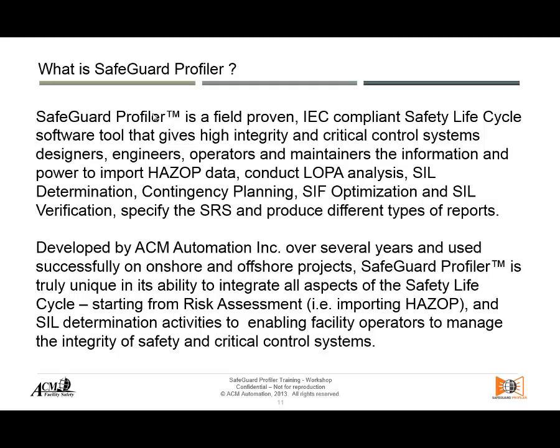So what is the purpose? Working in the safety field, functional safety field. And what is its scope? The scope would be the functional safety field. So it gives the high integrity and critical control system design engineers, operators and maintainers the information and power to, we will see later on, import HAZOP data, conduct LOPA, layer of protection analysis, which is a methodology for SIL determination. We'll also have the possibility to do risk graph analysis.